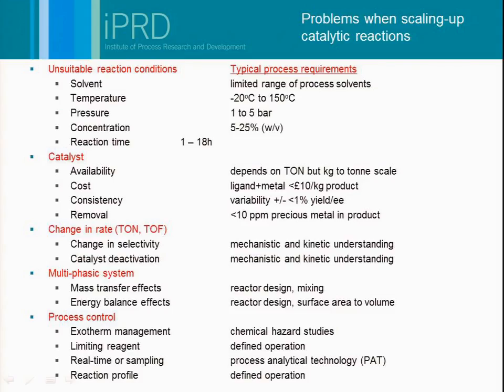But of course it's very often not. It's very often decomposing. And so we might get strange kinetic shapes in the reaction. We might even get, as I'm going to show you later, reactions that stop completely. So having some idea about the change in the catalyst performance, whether it's selectivity or some of that deactivation, can again be very important to having a process that's robust and reproducible.